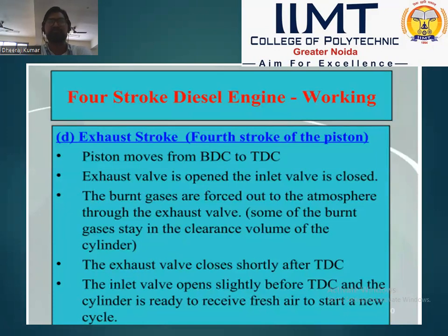The inlet valve opens slightly before TDC and the cylinder is ready to receive fresh air to start a new cycle. During the exhaust stroke, the piston moves from bottom dead center to top dead center.